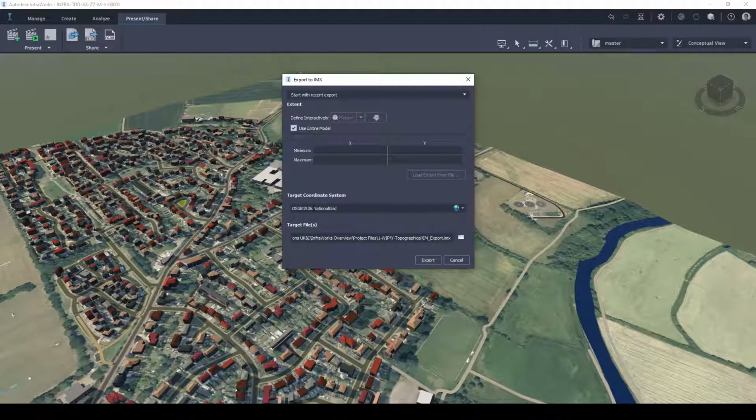I'd recommend using the same coordinate system throughout a project as good practice and to model everything geospatially correct, no matter the application used. This will mitigate against any coordination issues that may arise as the project progresses.